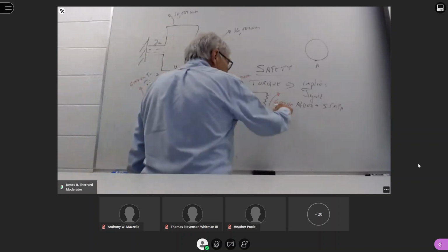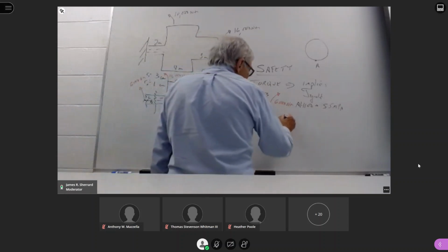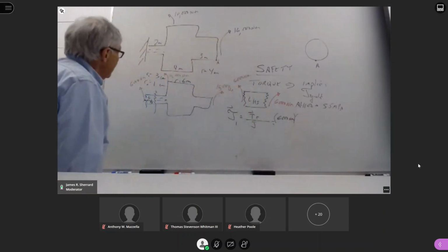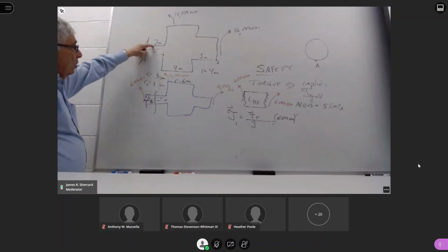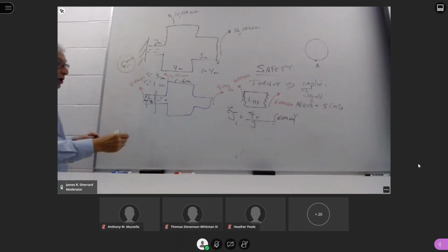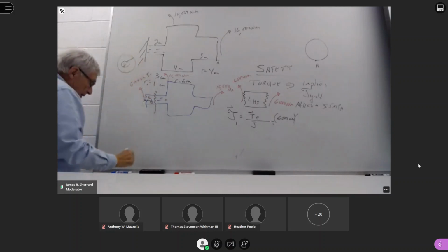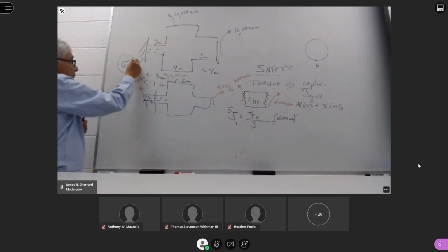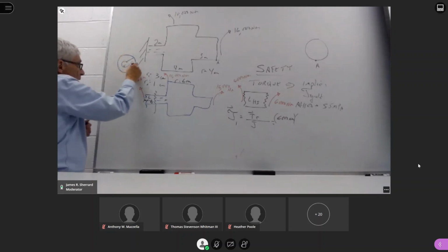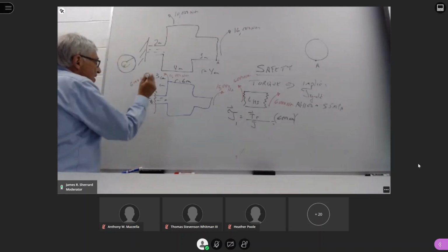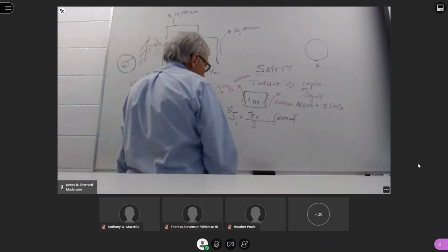In this particular case, we've just found that the torque applied was 6,000 Newton meters. The radius, we're going to use the outermost radius, because if this fails, it's going to fail first around this outer circumference. So we're going to use that radius in our calculation.